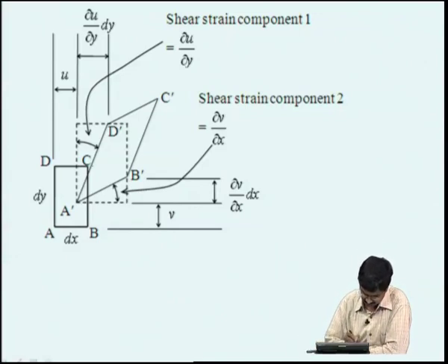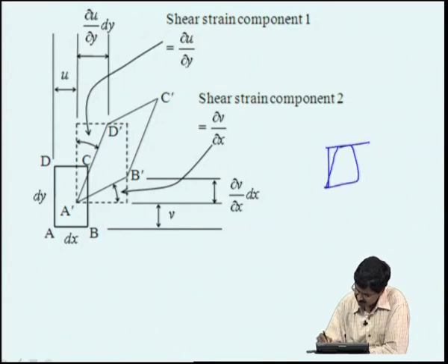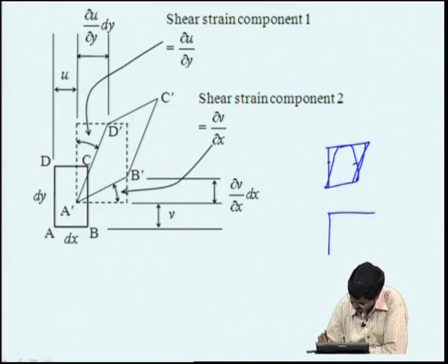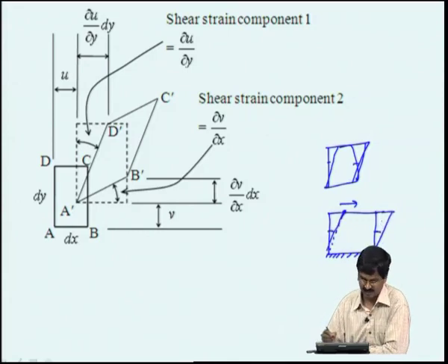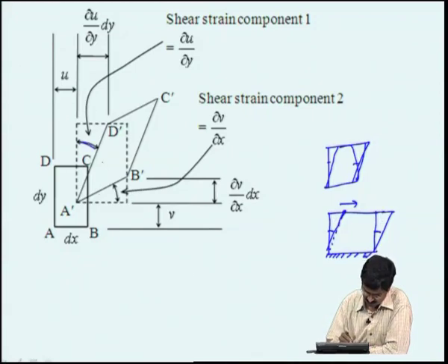We have the strain for the x axis and y axis which are normal strain, and there is also a shear strain where an element such as this gets sheared to that one, then we say these angles are the shear. Let us draw it properly. If I have that, let us say I hold this fixed and apply a force as we have done today. If this point moves here, this point moves here, okay, this angle and this angle are the shear strain.